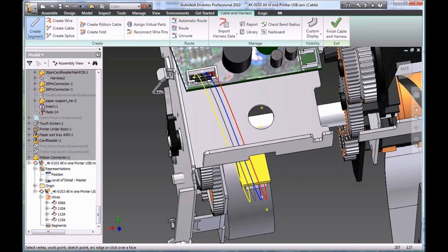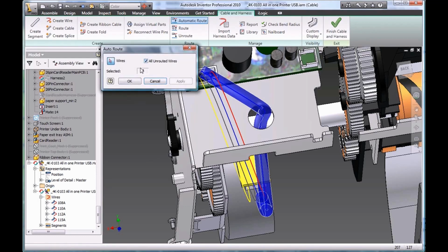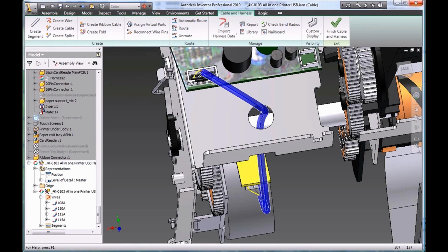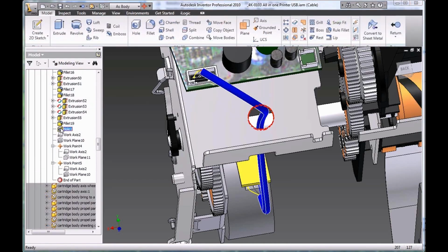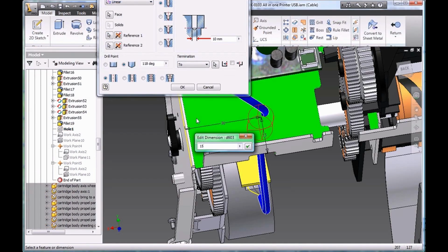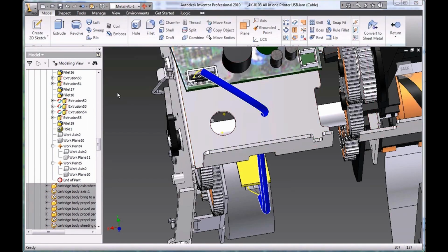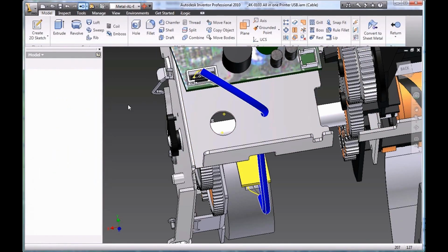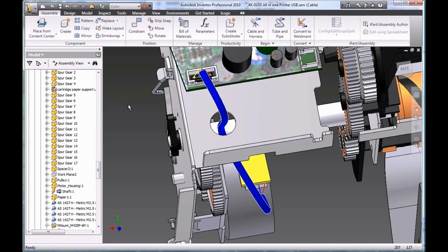Organize the resulting wires using multi-segment harness assemblies to define how you want the wires and cables routed through the equipment. Add points or move existing points to refine the overall shape of the harness and ensure proper spacing for manufacturing. Inventor creates associative relationships between the harness segments and the assembly geometry so wires move with their connectors, establishing and maintaining electrical intent even as the design changes.